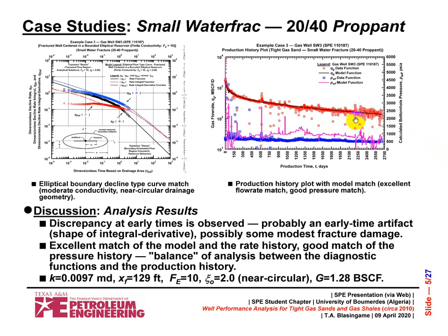You can see that as the well got older, there was more and more jumping around, which is indicative of liquid loading. But as far as the signature, this data set looks excellent, both for the pressure and for the rate. So it was history matched using this elliptical model.